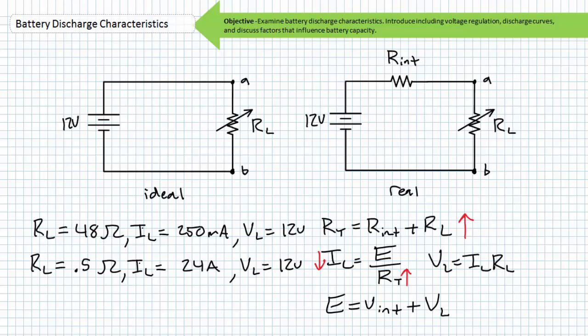Given our understanding of Kirchhoff's voltage law, what goes up must come down, it can be said that the voltage rise will equal the summation of voltage drops. What this all means is that not only will current be lower because of the internal resistance in series, observed voltage at the accessible terminals of the battery will be less than the ideal 12 volts when the load is actually drawing current. Given that both voltage and current decreased, power delivered to the load will proportionately suffer.